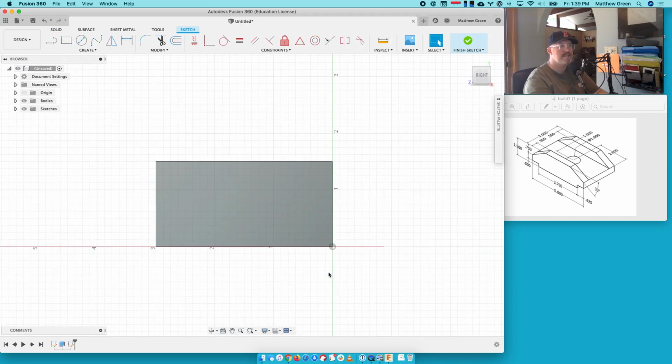I'm going to cut out of this side. What I know is these walls here are 1/2 inch thick, and I know they come down 0.75 inches. So I am going to use a line tool and come over 0.5 inches, use a line tool to come down 0.75 inches. And then, there are so many ways to do this. Just for kicks, we'll come over 0.5 inches again. And then I'll grab a rectangle and go from there to there.